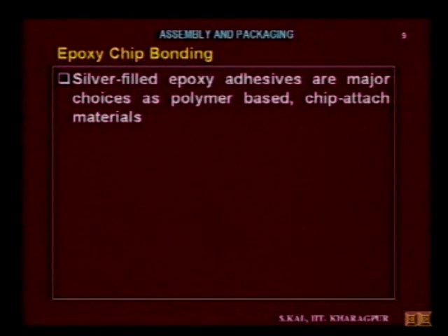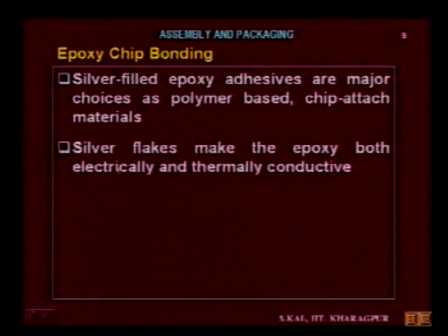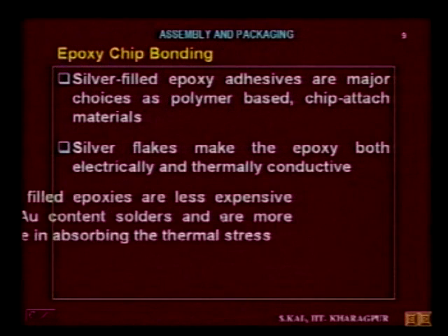Now coming to epoxy chip bonding. Silver filled epoxy adhesives are the major choice as polymer based chip attach materials. In these polymer materials, flakes of silver are mixed to increase thermal conductivity and electrical conductivity also. Silver flakes make the epoxy both electrically and thermally conductive.